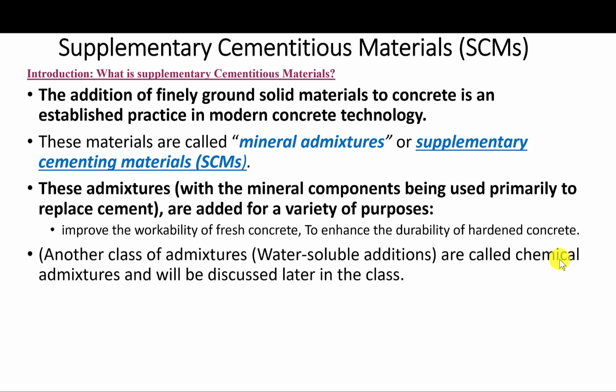Okay, so the addition of finely ground solid materials to concrete is an established practice in modern concrete technology. Collectively, these materials are called mineral admixtures or supplementary cementitious materials. Admixtures are added for a variety of purposes, with the mineral components being used primarily to replace cement.